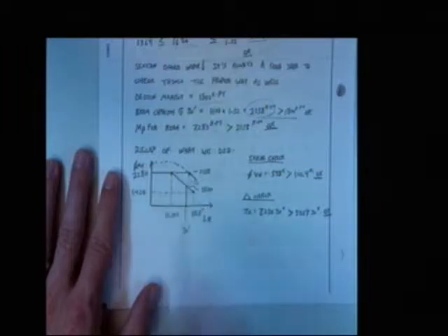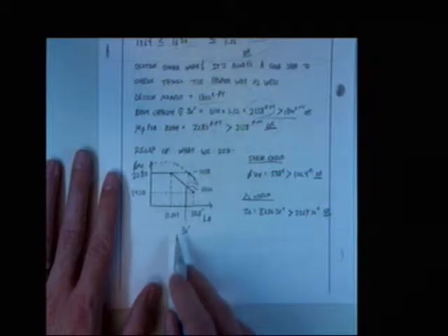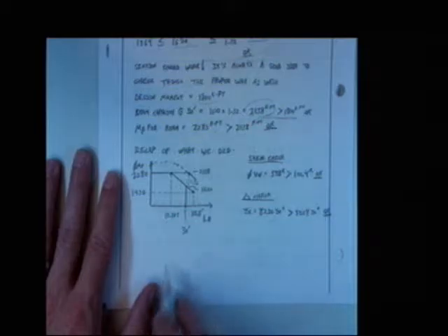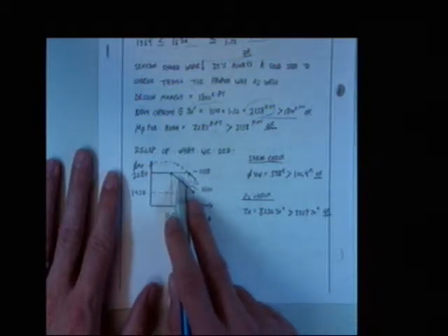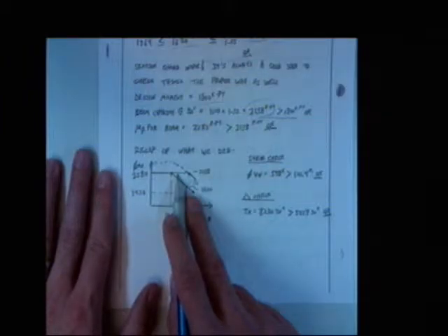Why? Because that's what the C sub B factor does. C sub B factor takes into account that I have a nonlinear moment diagram on my cross-section. Because I have a nonlinear moment diagram, the derived equations for lateral torsional buckling are very conservative, and I can up those capacities. I can do so up until the point where I reach phi M sub P, but I can never go higher than that.